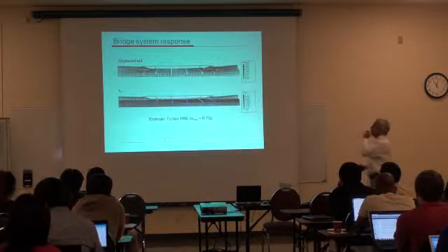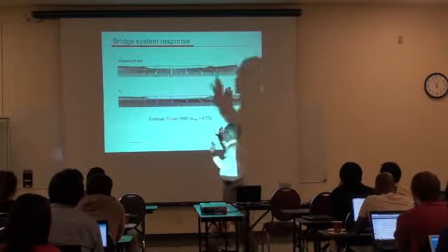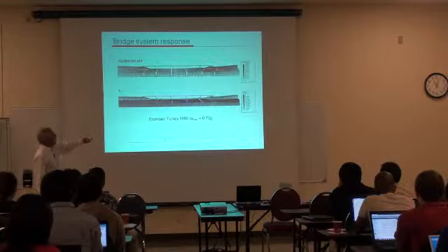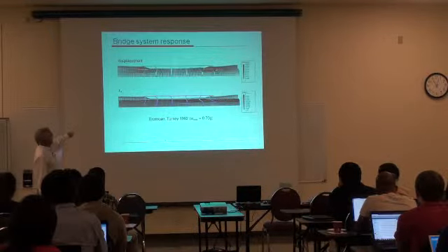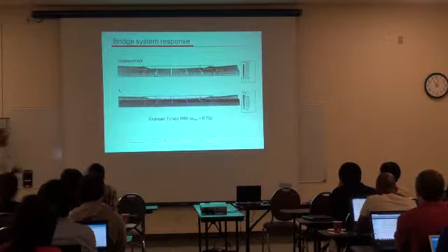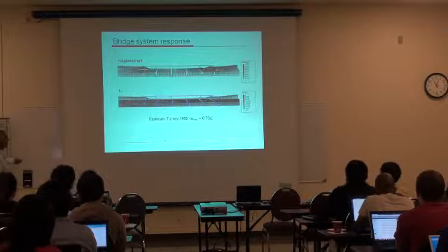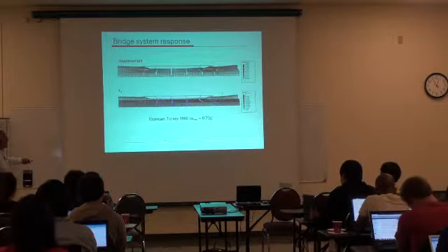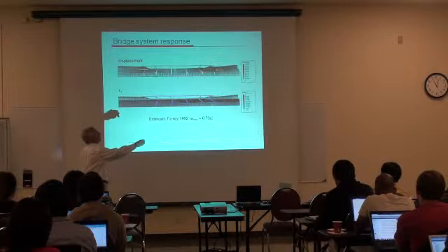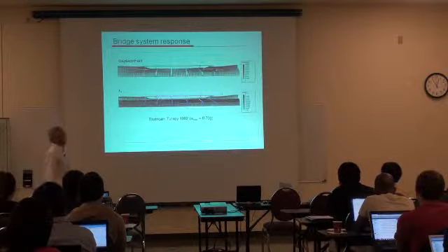I want to show you only one that indicates why to go and model the whole thing. The thick liquefiable layer was on that side. The liquefiable layer here was much smaller. Here you see the pore water pressure ratios in black. So you see how thick the liquefiable soil was, and the thickness there. Now, we observe here a lot of deformation, 90 centimeters in our predictions, only 20 centimeters in that location.